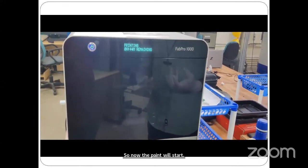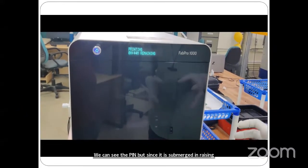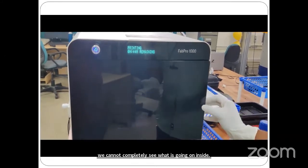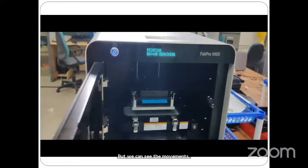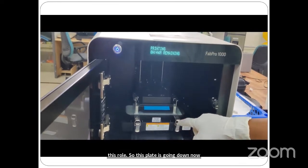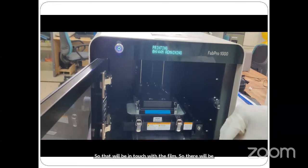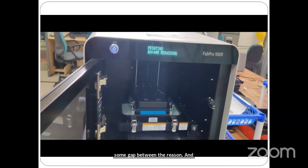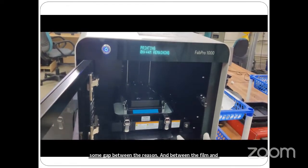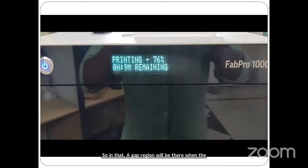We can see the print, but since it is submerged in resin, we cannot completely see what is going on inside, but we can see the movement. So let's say I'm opening this door. So this plate is going down now, so that will be in touch with the film. So there will be some gap between the film and the build plate surface. So in that gap, resin will be there. When the projector projects the 2D cross section to that area, that will get cured.